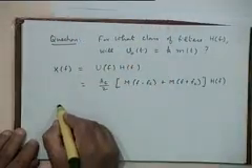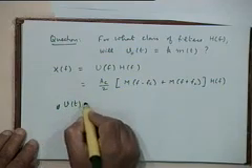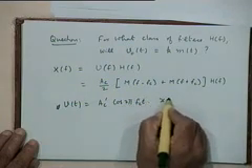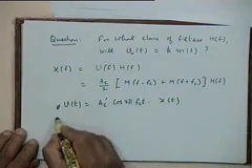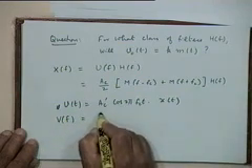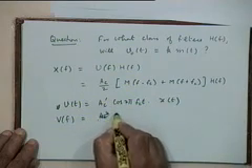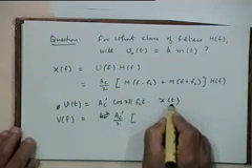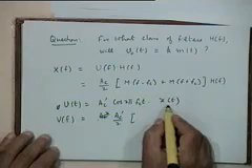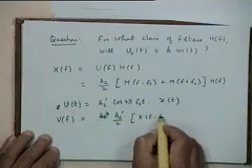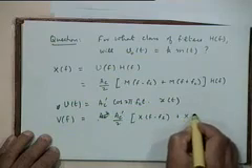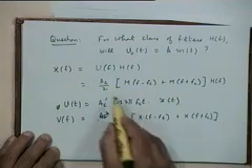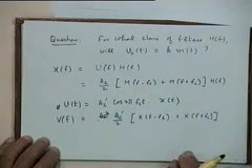If I define v(t) as A_c prime cosine 2 pi f_c t times x(t), which is what I am doing, your V(f) will be A_c prime by 2 into just the translation of the spectrum of x(t), so X(f minus f_c) plus X(f plus f_c). But X(f) is given here, so can I substitute that here?